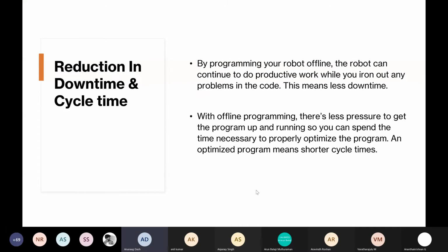And then, reduce downtime and cycle time. In the beginning, I talked about the very same thing. While you code, the program is running, and you can simply upload your code, which changes it. Downtime is basically when the machines aren't operating, and cycle time is the time from the beginning to the end of your process, defined by you and your customer. That is when your work is being acted upon, plus the delay time it spends waiting. You can reduce that using offline programming because there are low switchover times. So all in all, there are low cycle times.